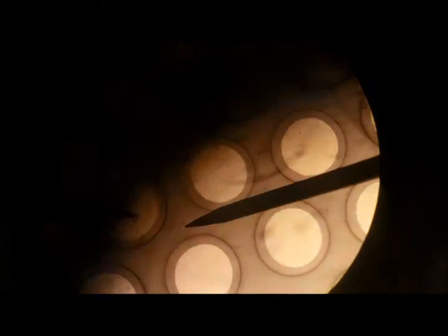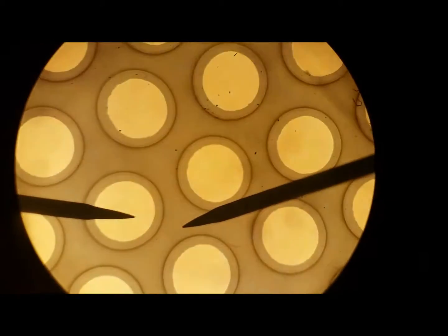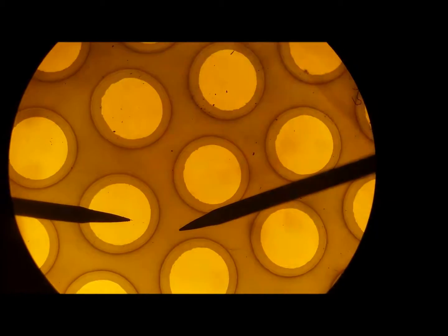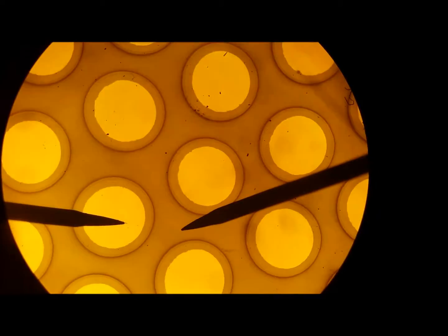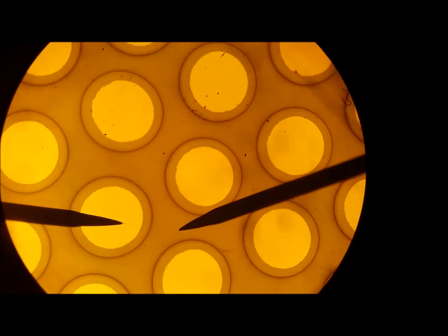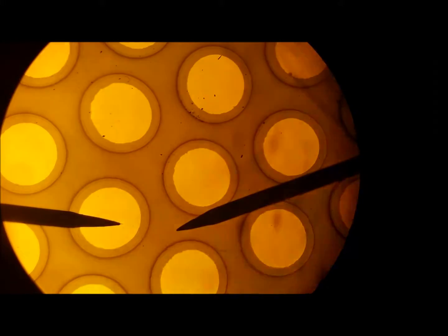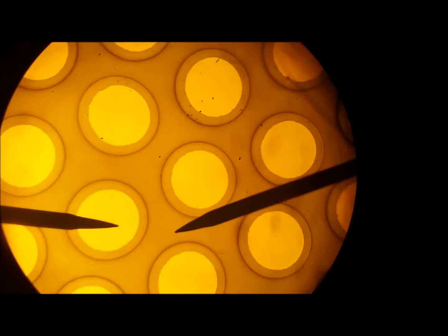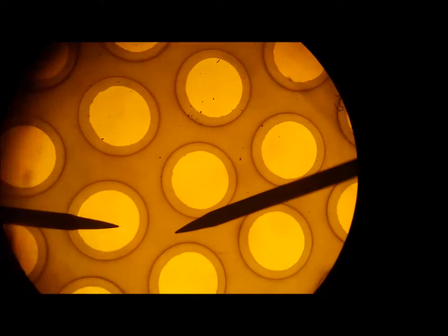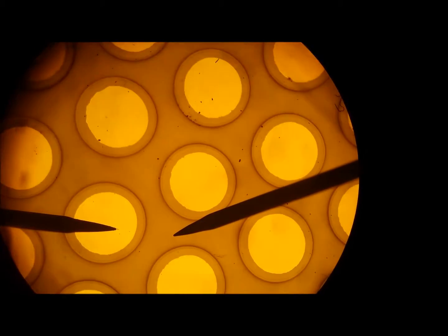Let's take a look through the microscope. As you can see here, these are our 2 probes. The rightmost one is controlled to be placed onto the silicon dioxide. The leftmost probe is placed onto the aluminum contact. Since there's doped silicon underneath the aluminum contact and the silicon dioxide, we would expect a MOS capacitor.